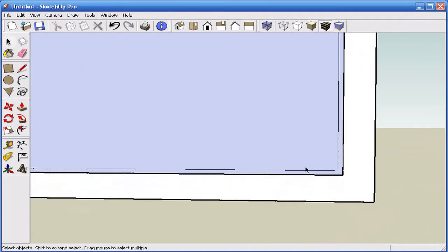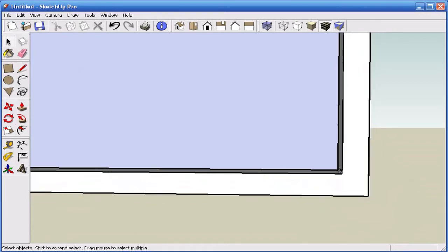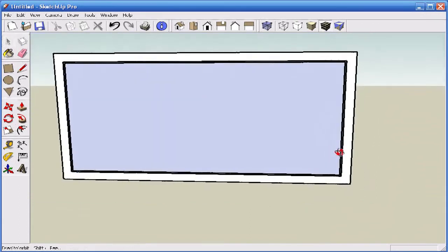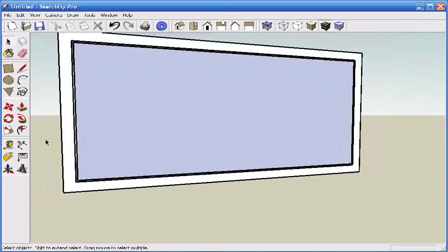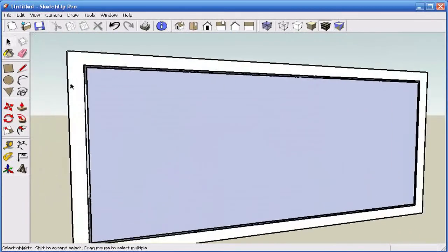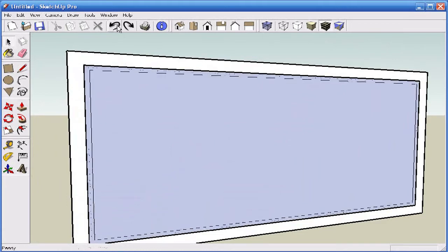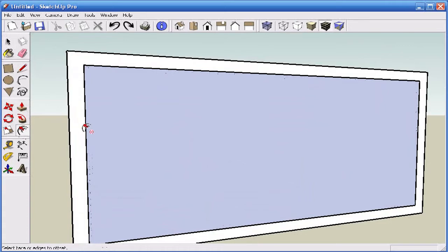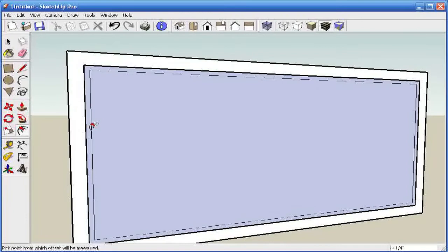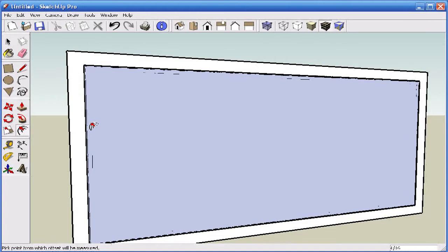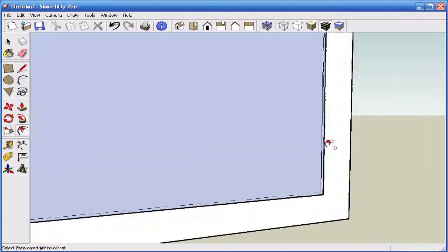Then use the select tool to select the gap area between the case and push the delete key to eliminate that one area. So you've eliminated the gap area around the drawer case, around the drawer face, and it's a 1/8 inch. Oh, you're a fastidious carpenter, huh? Well then, let's make that gap a 1/16 inch. So we'll change the gap by using the offset tool. We'll bring that offset in, and we'll make it 1/16 inch and press enter, and now we've got a real tight clearance around that case.